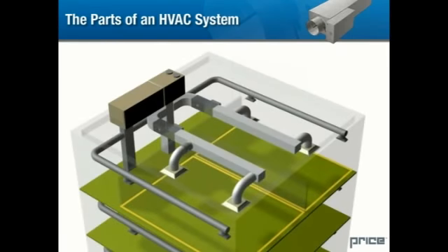The diffuser's job is to direct the airflow throughout the occupied space in the most efficient manner possible. More information on desirable air patterns is provided in the space air diffusion section. We will discuss diffusers in more detail in air outlet selection.